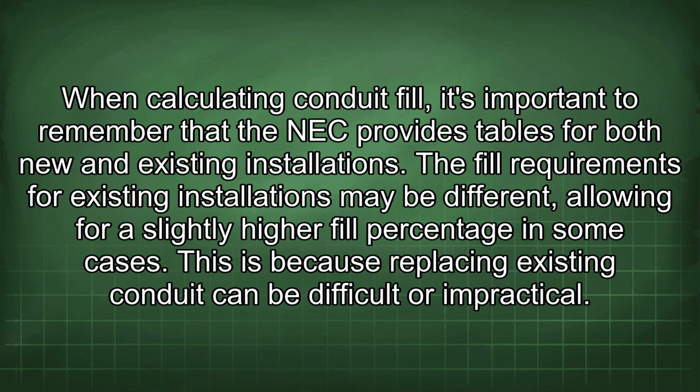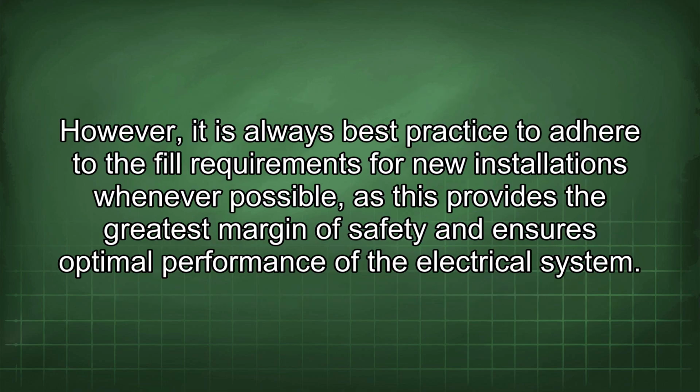When calculating conduit fill, it's important to remember that the NEC provides tables for both new and existing installations. The fill requirements for existing installations may be different, allowing for a slightly higher fill percentage in some cases. This is because replacing existing conduit can be difficult or impractical. However, it is always best practice to adhere to the fill requirements for new installations whenever possible, as this provides the greatest margin of safety and ensures optimal performance of the electrical system.